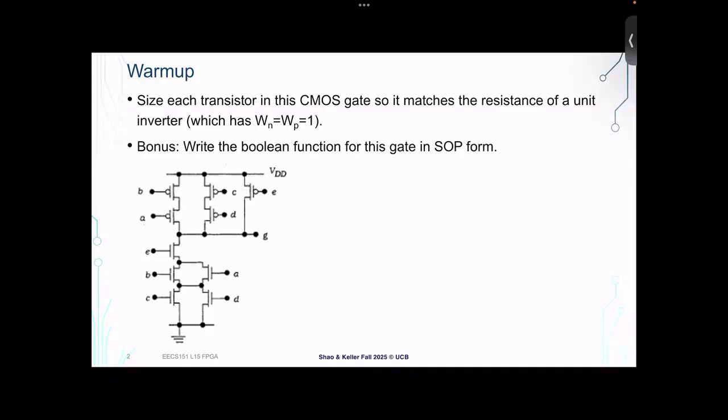is something pretty fundamental to understanding gate sizing in digital circuit design. Yes, question before we go over the answer. Non-integer size. You can use non-integer sizes, yeah. In a FinFET process, that's actually problematic, but let's hand wave that away for now. One of the nice things about gate all around is that it actually lets us once again go back to arbitrarily sized transistor widths rather than being restricted to an integer number of fins as we are in FinFET process.